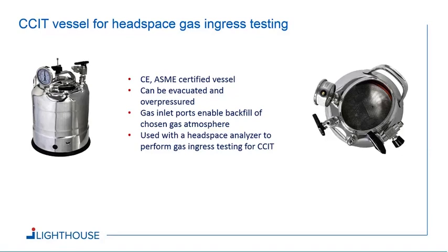And then after you've put the samples through a particular cycle in the vessel, you can then remove them, and you use a headspace analyzer then to perform gas ingress testing, looking for a determination of the container closure integrity.